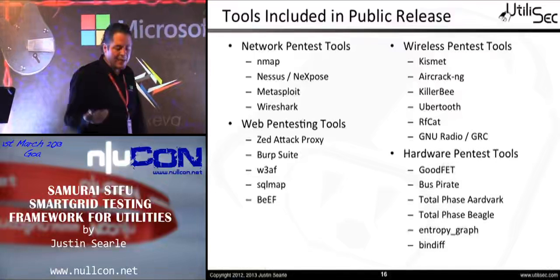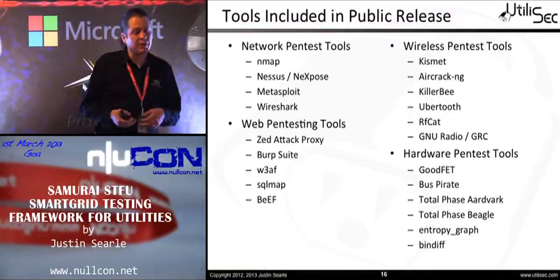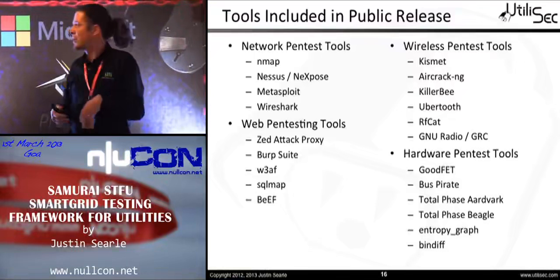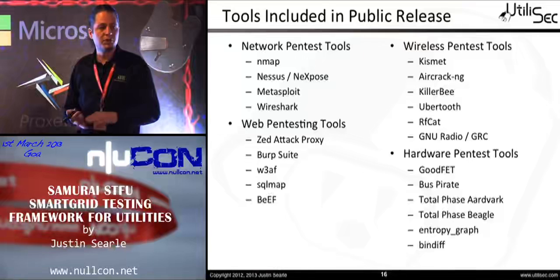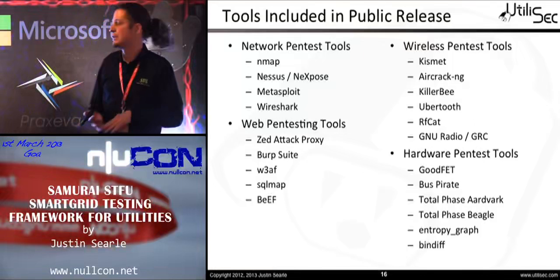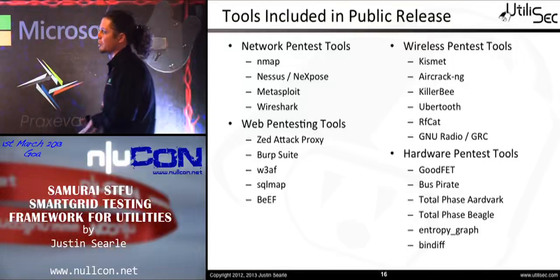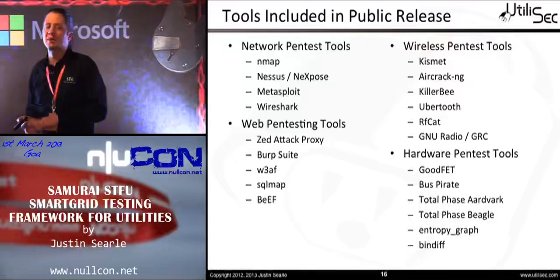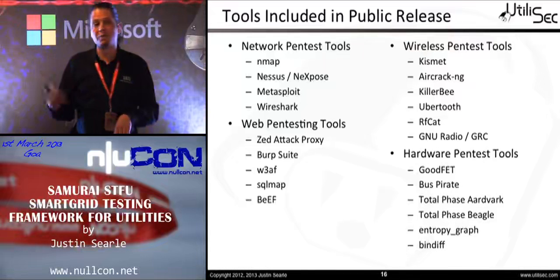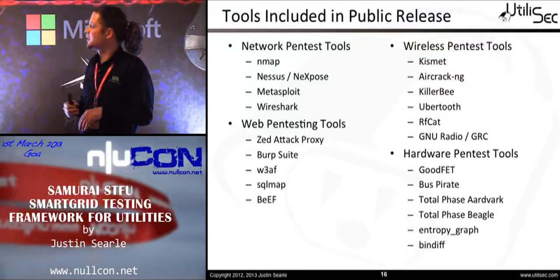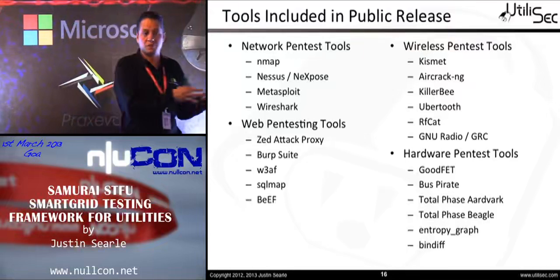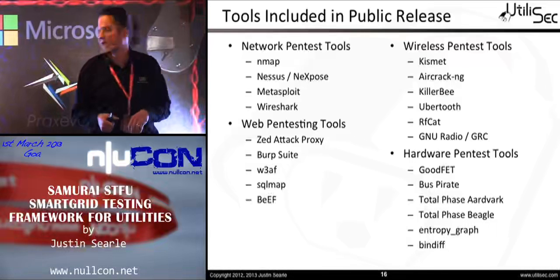So in capturing and doing the analysis on the embedded boards and doing bus snooping, we have a couple different tools that are available. The first two are good community tools, GoodFET and the Bus Pirate. Both are very, very excellent tools for doing different types of attacks in the embedded space. We have more commercial tools like Total Phase's Aardvark and Beagle, which happen to have some open source libraries, which I'll be including inside of the distribution. So if you have the commercial tools, you can still use those libraries.